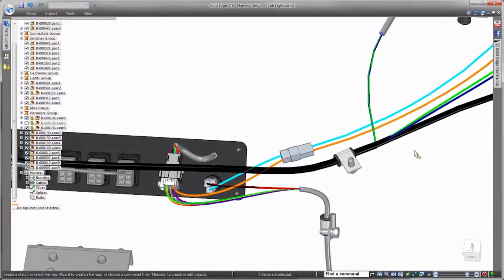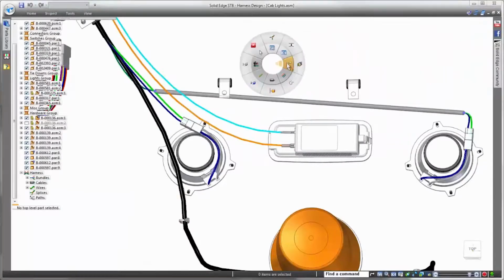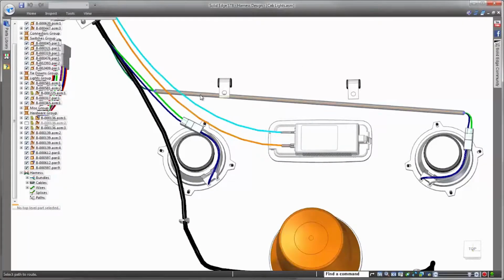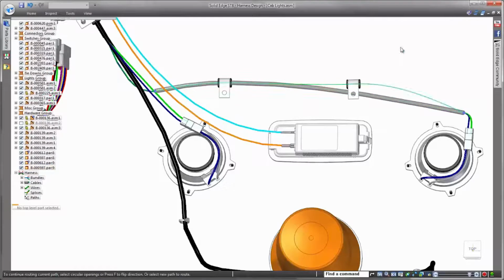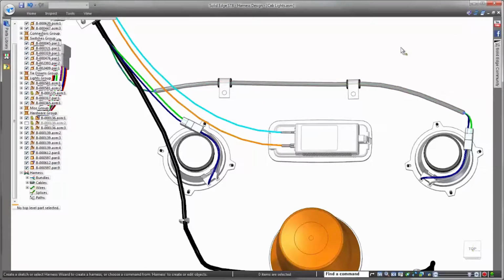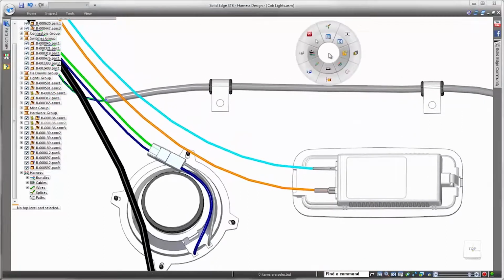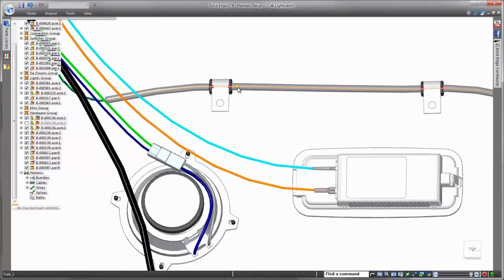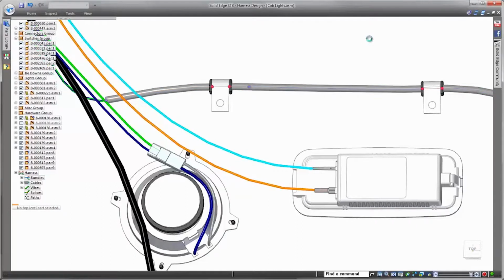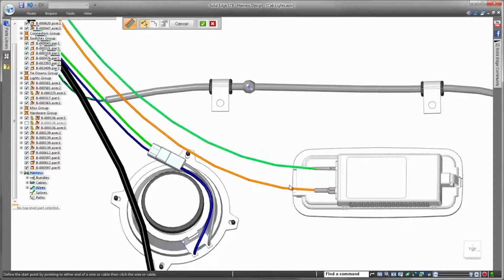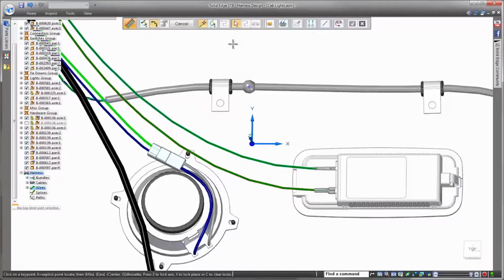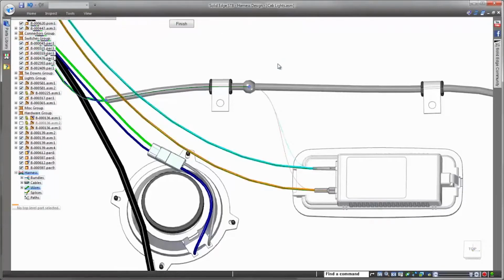properly wired and placed. We've seen how easy creating a new path is, but what about rerouting cables that have already been placed? Not to worry, that's even easier. Select the cable, select the clips, and Solid Edge handles the rest. But what happens if we need to add additional wires into an existing cable or bundle? Here, we need to clean up the interior light wires to combine them with the main harness. While we could easily create and route another path, why not just simply split an existing path and add the wires there, using that existing route location to easily clean up the harness.